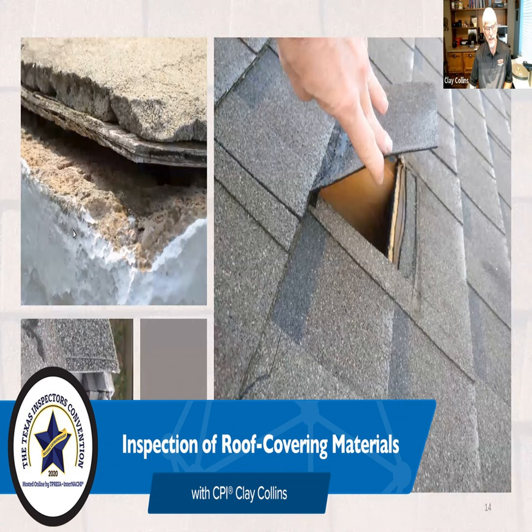You have an asphalt roof that is laminated, so you take what appears to be a 3-tab and you start laying pieces on it. By the time it's all said and done, it emulates a shake roof or a shingle roof, the way they used to do it with their lapping. The architectural shingle then is thicker, and so it has a longer life.